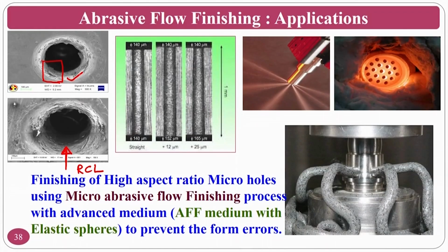As I said, casting means melting, then you put it into the mold. Here there is no mold, but the molten material solidifies again. That is why this resembles a casting technique, and the layer formed here is a recast layer. You can see here how the recast layer is there. If you put this component in a practical application, it is going to fail as early as possible. For that purpose, you should always try to finish this surface so that you remove the recast layer and the life of the component increases.